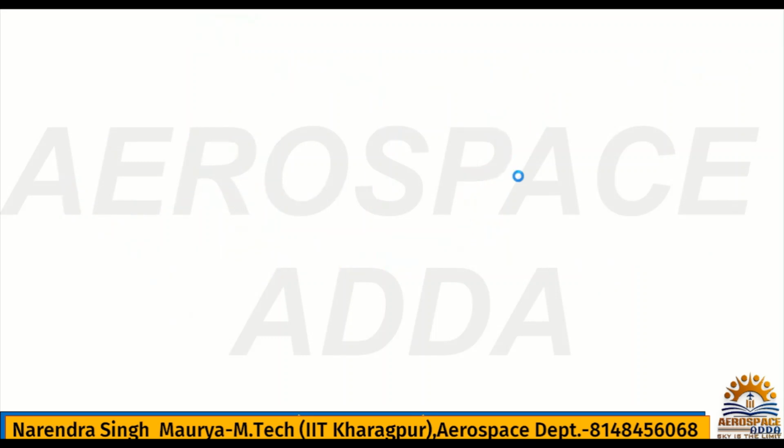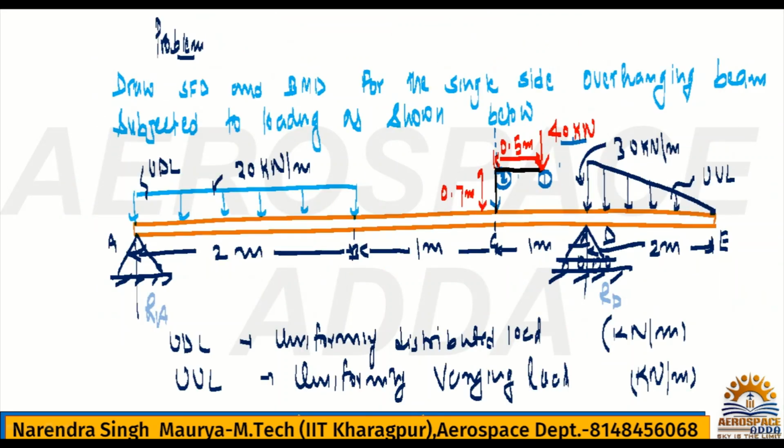This type of bracket load always generates a moment also, 40 into 0.5, because this is the perpendicular distance. You are taking moment about point 2 or point C, because C and 2 are the same, as the line of action is the same. If you draw the line of action, C and 2 are both on the same line, so taking moment about C or 2 means the same.